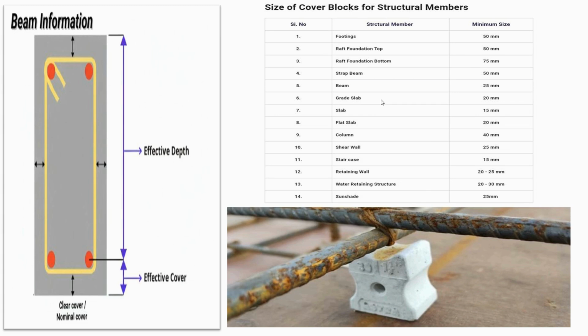I mean, it transmits the load directly to the ground. There's a difference between transferring loads and transmitting loads. Loads are transferred from one structure member to another. For example, a load will move from a slab, it will be transferred to another structure member. It might be a beam. From a beam, it will be transferred to a column. From a column to the footing. From the footing, it is transmitted. So that is the difference between transmitting and transferring.